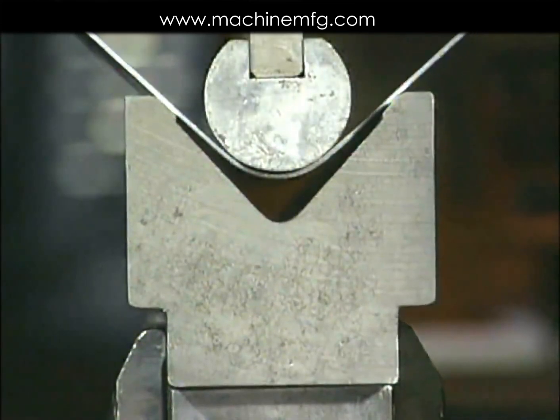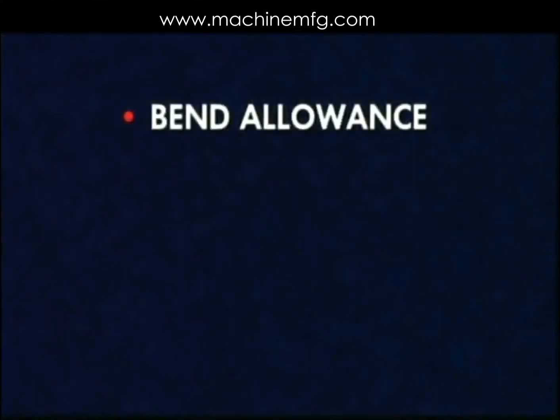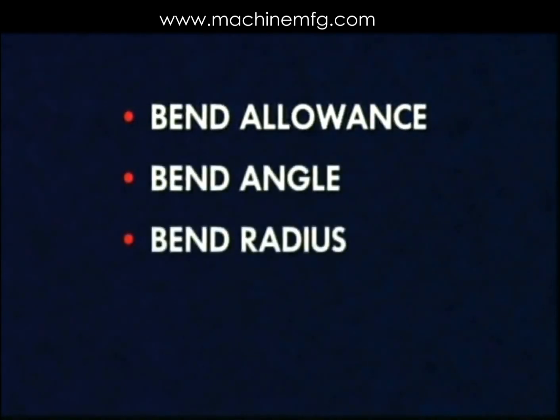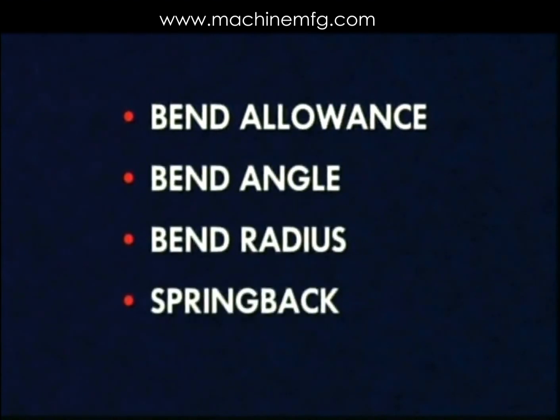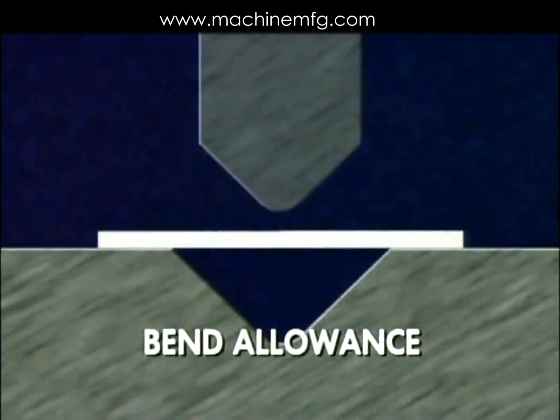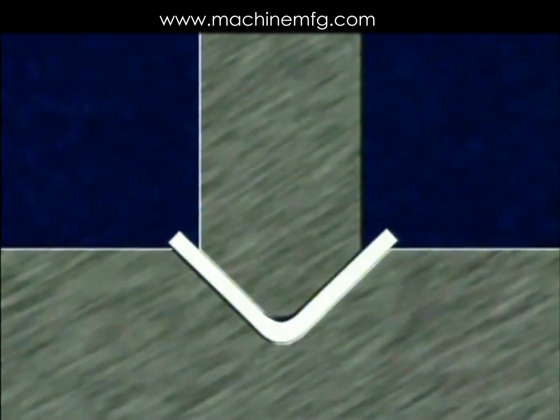The principal terms used to describe bending on press brakes are bend allowance, bend angle, bend radius, and springback. Bend allowance is the pre-bent length of material that must be included in a blank to allow for any deformation that occurs due to the bending operation.